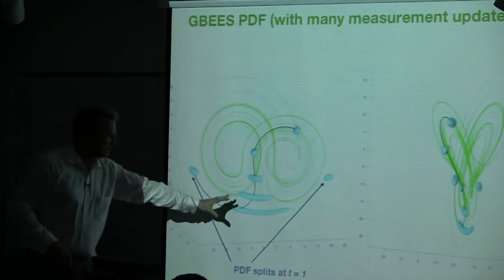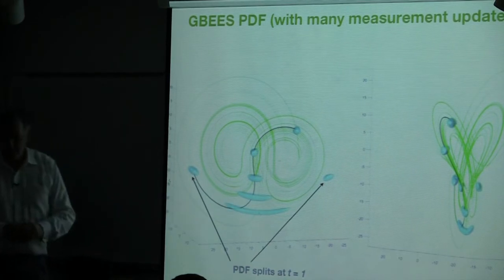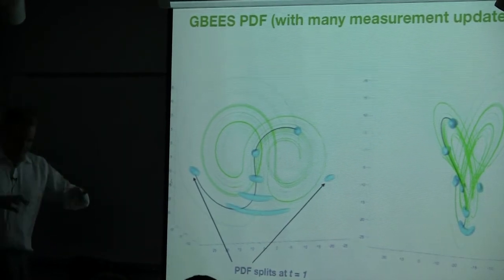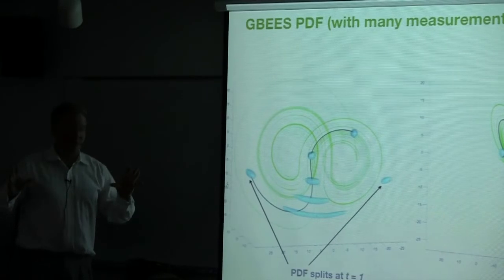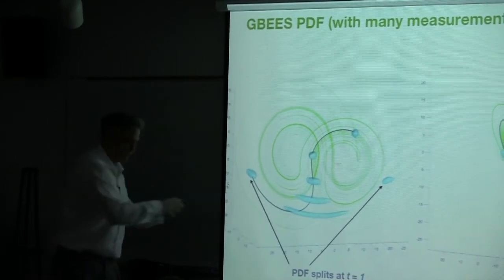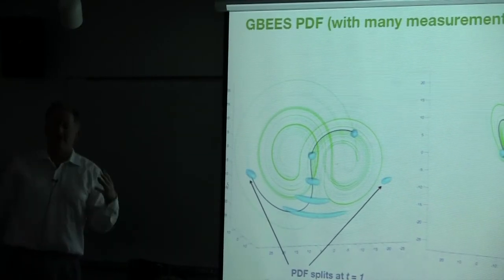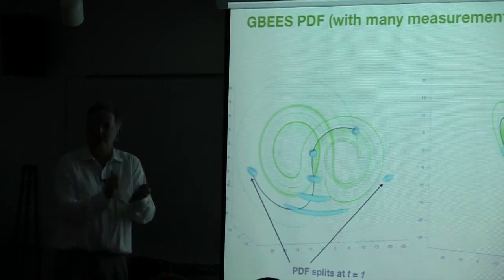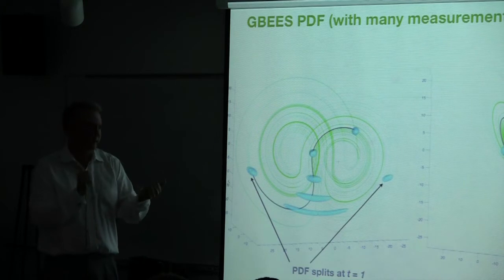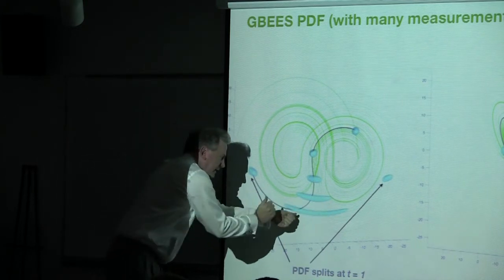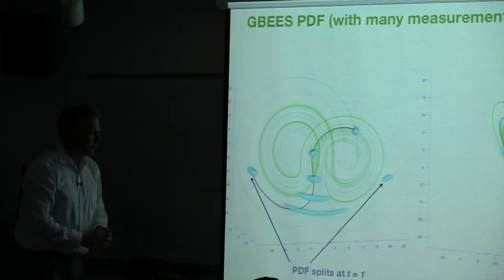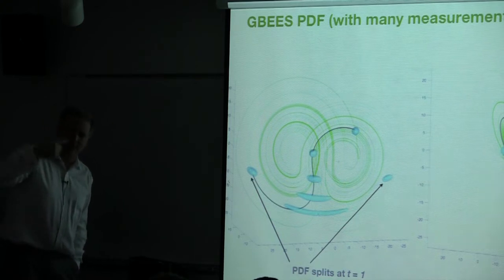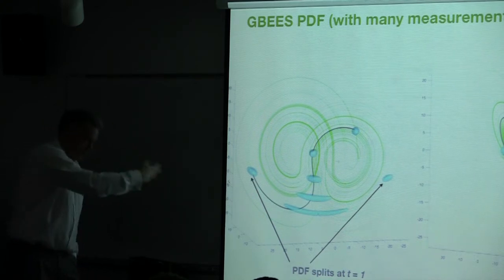But we have a mostly Gaussian distribution of uncertainty. What I need of the covariance matrix, which describes the shape of this football, I don't need the whole football. What I need to do is I need to identify the principal directions of uncertainty of that covariance matrix. I need to find its primary eigenvalues because it's those directions that I'm going to update when I do a Bayes update.